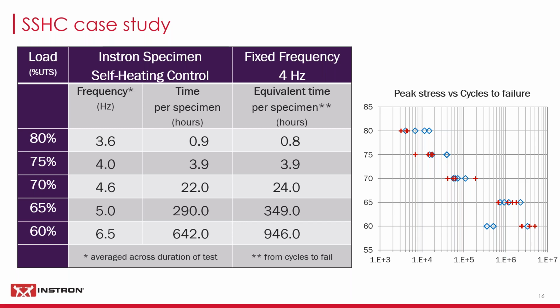Similarly, if the temperature starts to drop off because it's actually getting into a more stable state, then it will increase it. So it really is just there's an algorithm which gets you up to specimen temperature, and then once you're in a steady state, then you have a similar sort of command versus feedback error kind of system. It's not PID, it's not like that, but there are similarities in how it behaves. Sorry if that wasn't very clear, slight distraction in the middle there.